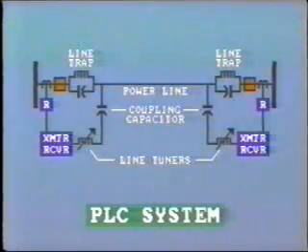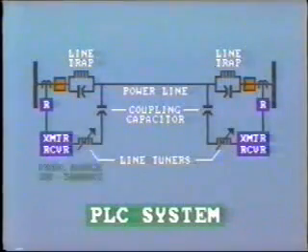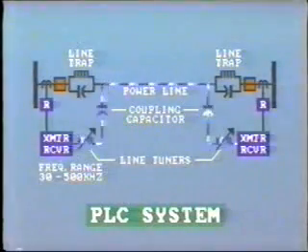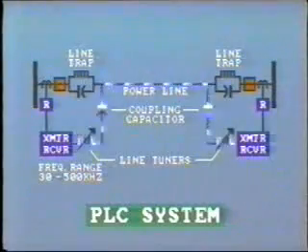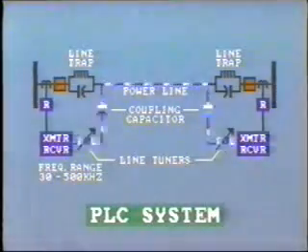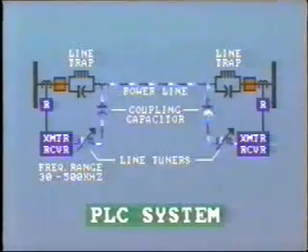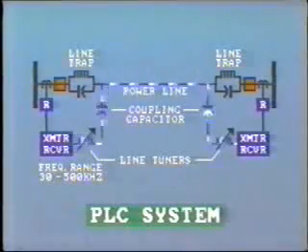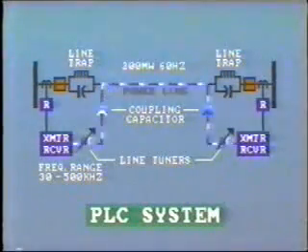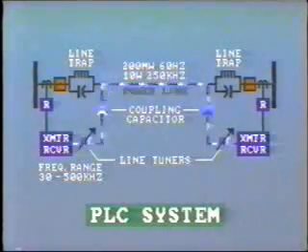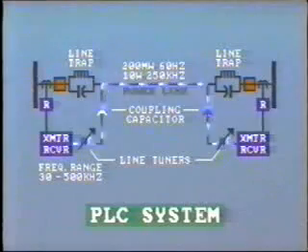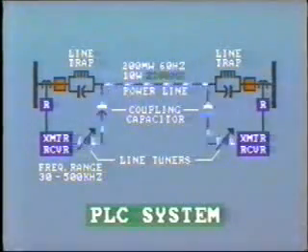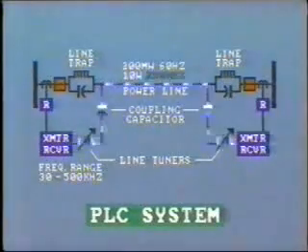In the power line carrier system, the signal is transmitted at a specific tuned frequency selected within the range 30 to 500 kilohertz. This high-frequency signal is superimposed upon one of the power line conductors, usually the center conductor, so as to reduce the effect of mutual inductance. The power conductor provides the metallic path for the signal. The power line, in fact, is carrying, say, 200 megawatts of power at 60 hertz and 10 watts of signal at 250 kilohertz. The first question is, how do we confine this high-frequency signal to the line itself?